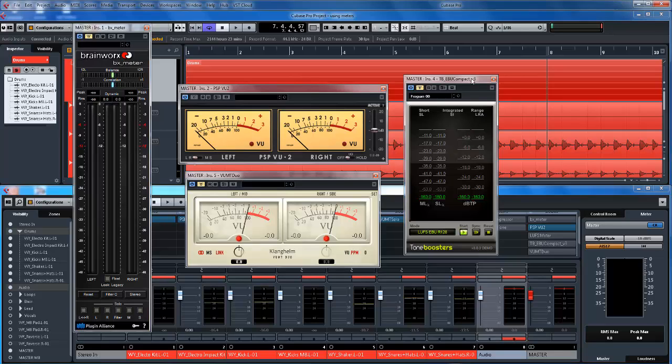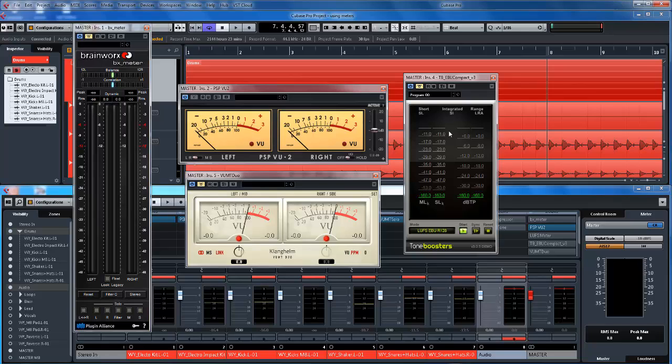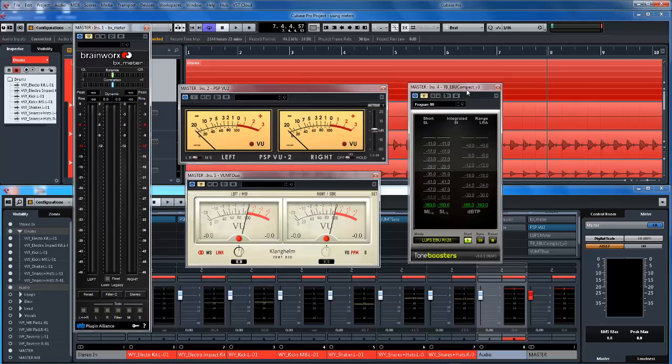So now we ended up with true peak meters. These have to show true peak levels because any overloads in the digital system will cause aliasing distortions. In other words, as I said earlier, we have to calculate intersample peaks. And this thing does. Now, the typical 4 times oversampling true peak meter, which would be this, is only accurate to 0.7.